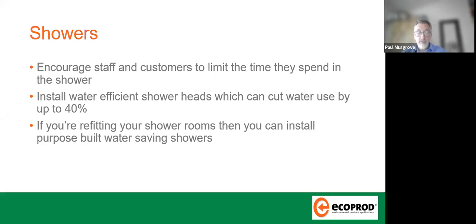That can be overcome by using shower panels, and of course, digital solutions and timer controls, which may be providing showers with fixed time flows. Again, trying to encourage people to think about how long they're showering. Flow rates of showers are mostly related to your water pressure on site. And typically through the UK, we come across showers in commercial buildings, which may be 5 and 10 and 15 years old in use, which are delivering upwards of 20 litres per minute of water.